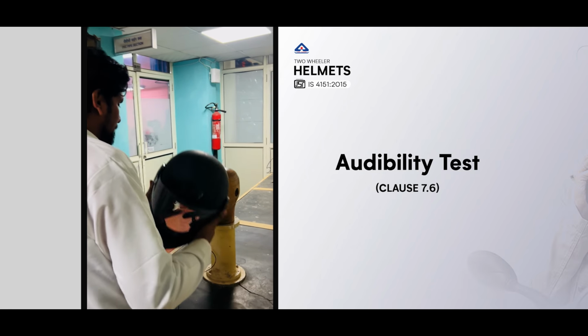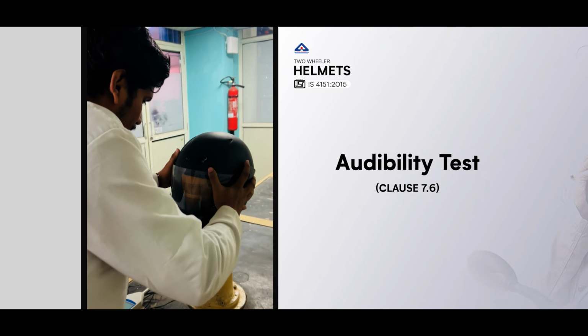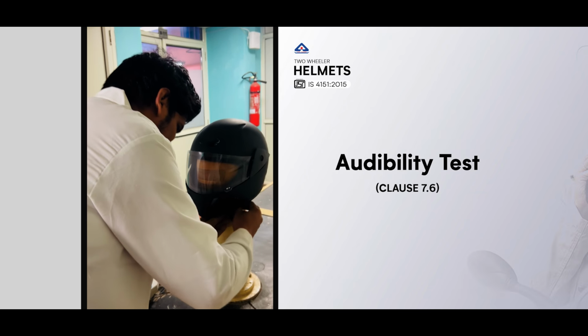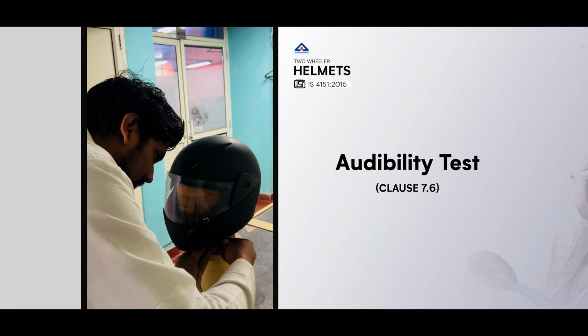Audibility test, Clause 7.6. This test ensures that the helmet allows proper sound transmission. The sound level difference between front and back must meet standard limits, with a horn producing 90 to 115 dBA in a noise-free environment.